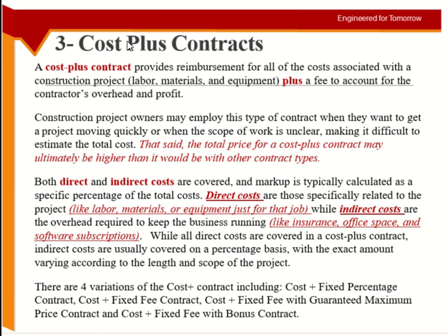Okay, so in the previous one, in the lump sum, you need to know everything to give the total cost. In the unit cost method, you need to at least know the type of work. I don't know the quantities. Like the example which you did, it's a highway project. At least I know the type of project, right? I know the type of work which will be in the project. I don't know the quantities. I can say, okay, I will increase the highway by 1 kilometer. But I cannot say I will now not build the highway and have a bridge.